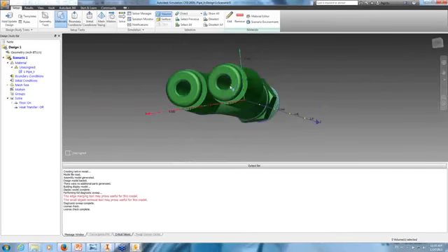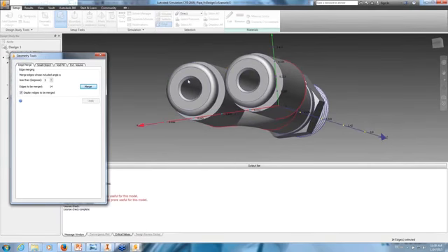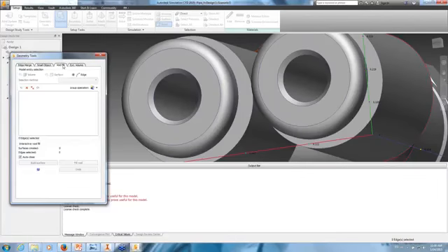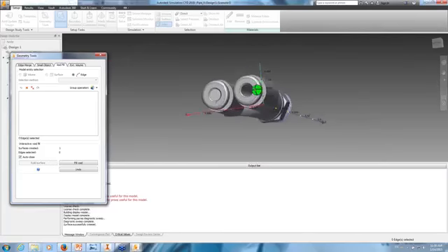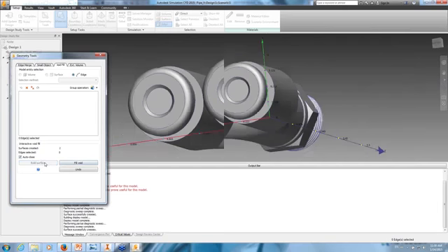So how do we generate the fluid inside of it if we didn't do that already in our CAD model, which most people don't? To do that, I will go to the geometry tools. Basically what I need to do is plug these 3 holes, create surfaces to plug these holes, and then I can generate the volume inside once it's watertight. That's going to be quite easy here. I'm going to go to the void fill tab here, and select edges. So I'm going to select this edge and build the surface. Zoom back in and select this edge and build another surface.